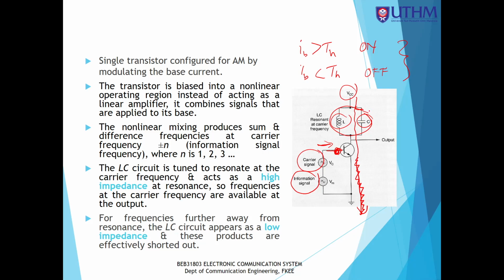So this LC tank circuit will resonate during the negative cycle of the output signal, and it will fill in the missing half negative cycle. So we produce a full wave at the output. Remember, the LC tank circuit will only resonate during the negative cycle of the mixing input.